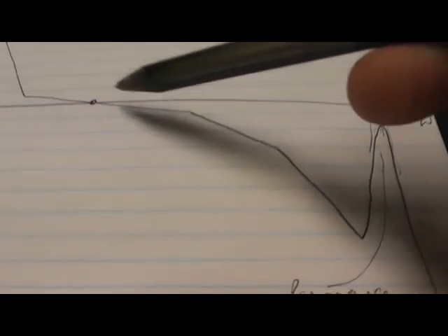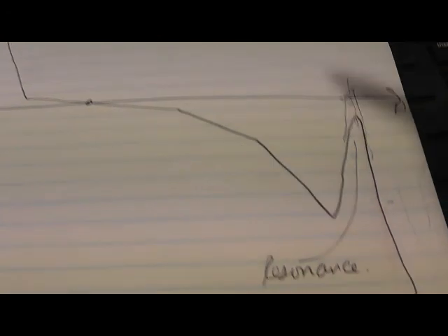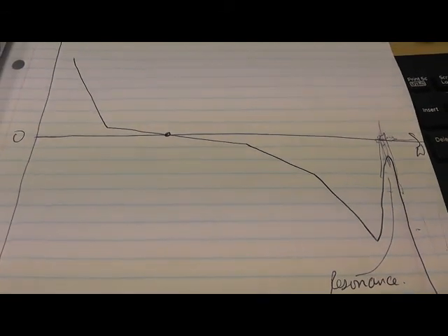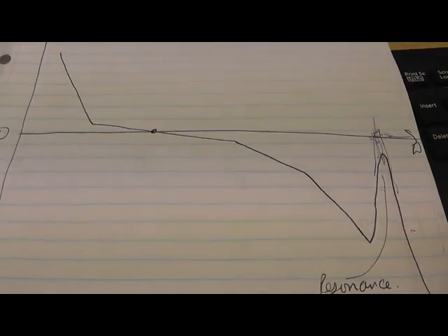So what happens is you get a stable response, and the oscillations due to this guy at that frequency are superimposed on top of the response. This is called a parasitic oscillation. Slightly different in op-amps, parasitics, same kind of idea, but of course in op-amps it's maybe slightly different reasons.